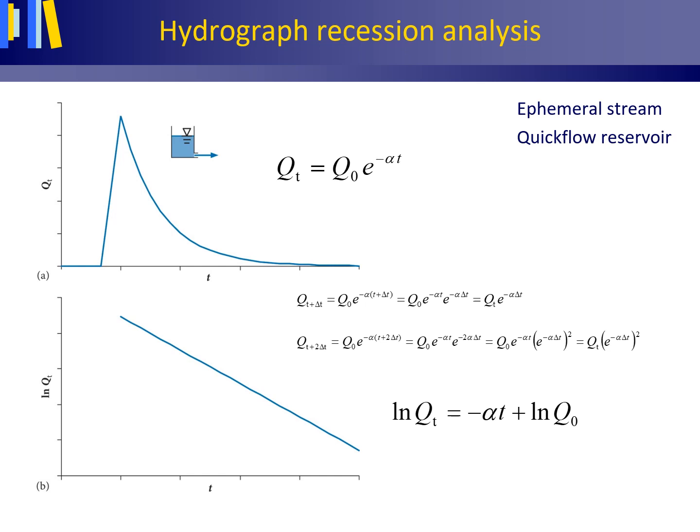This sheet shows a hydrograph of heavy rain on a wadi, a usually dry riverbed in a semi-arid climate with the exception of periods during and shortly after heavy rainfall. A wadi thus is a type of ephemeral stream and its discharge is made up solely of quick flow. For an ephemeral stream, the recession curve can conceptually be interpreted as outflow from a quick flow reservoir. The recession curve can mathematically be described as an exponential decrease starting at the hydrograph peak, as shown here.